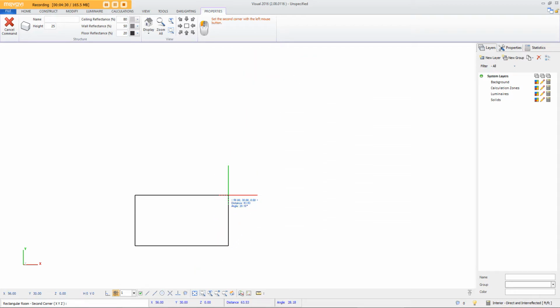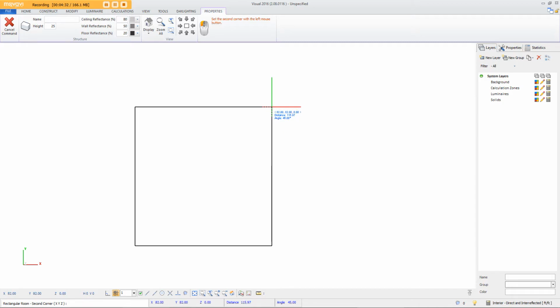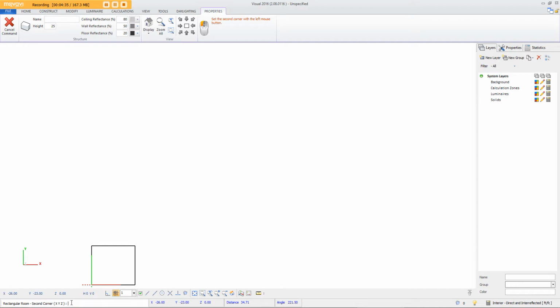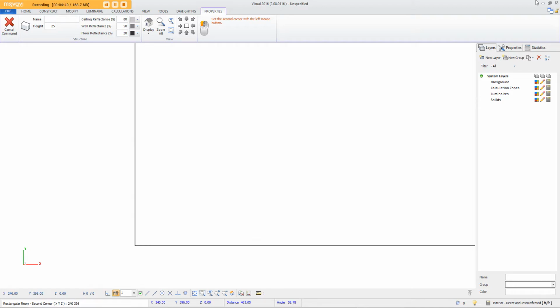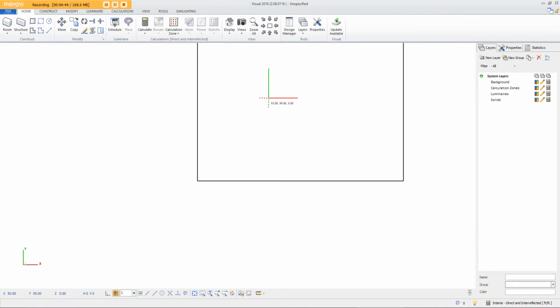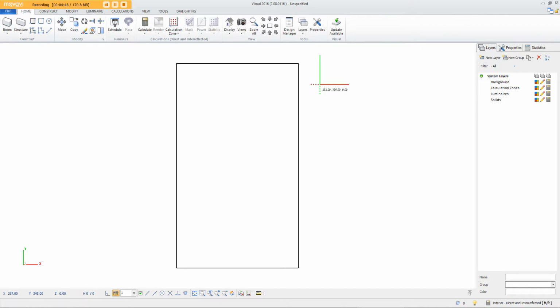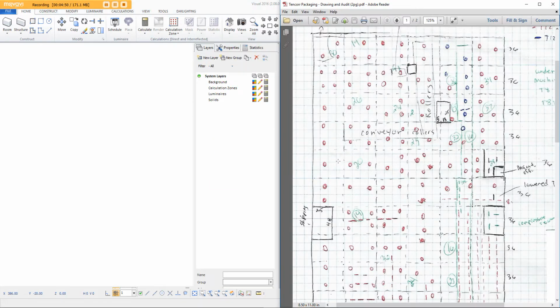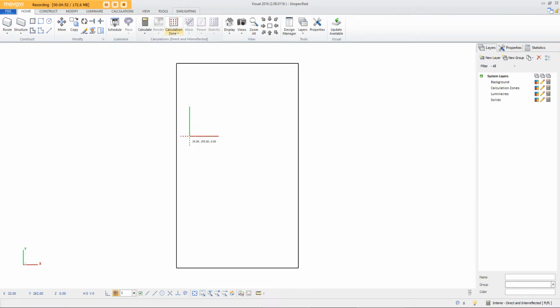You can also see them by my cursor. What we need to get to is X 240 and Y at 396, so I can just put those in for now. 240 space 396, enter, and that's going to give me a huge rectangle, which I will then scale back or press Z for full screen. So here's that outline that we're seeing here, starting to come together. Next thing is we're going to get the line out.